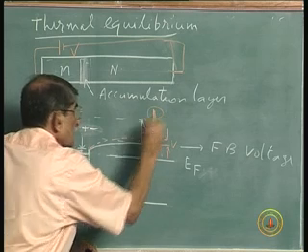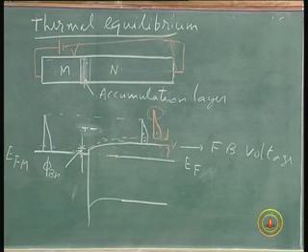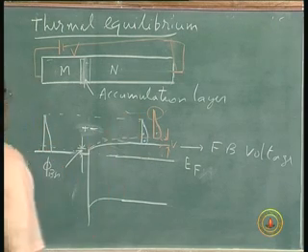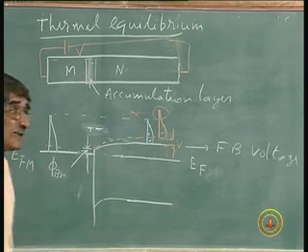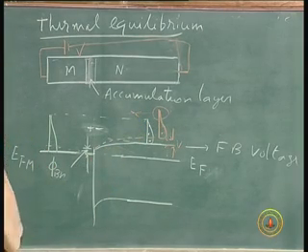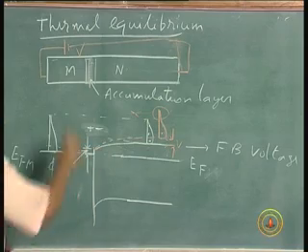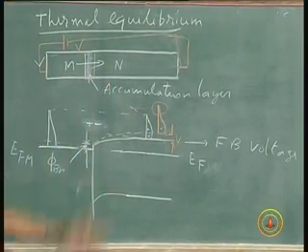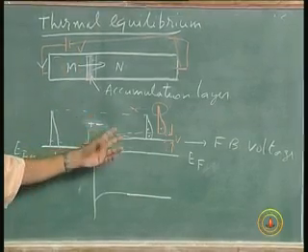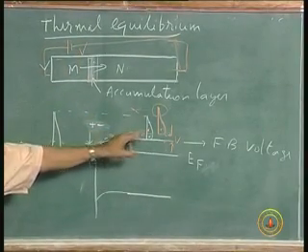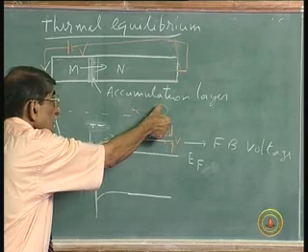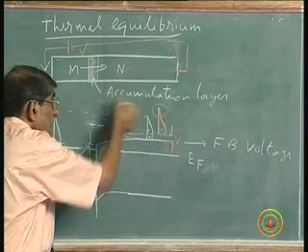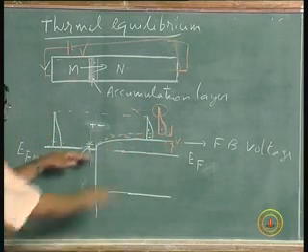So, the electron energy has gone up there, the extra electrons now have energy to cross the barrier. They will give rise to electron flow in that direction, which gives a current flow metal to semiconductor. Battery has to drive the current only in that direction. So, this lifting up has enabled additional electrons, a large number of electrons are there, they can cross. If it pushes down, what happens?